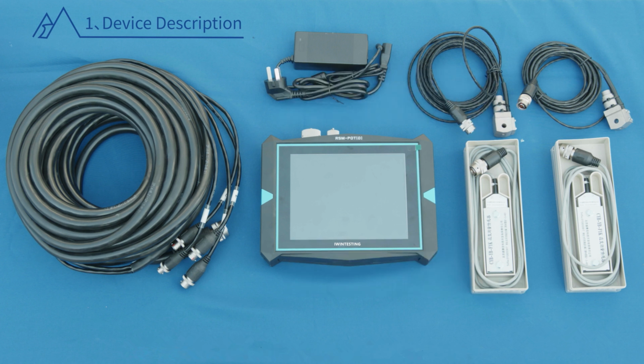In addition to the host and supporting accessories, sensor installation tools such as electric drills, expansion bolts, and wrenches should be prepared for high-strain PDA testing of foundation piles.